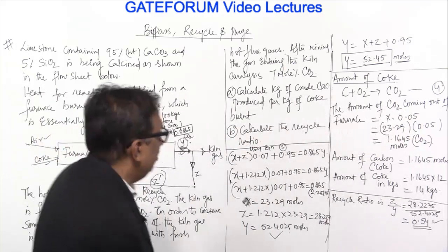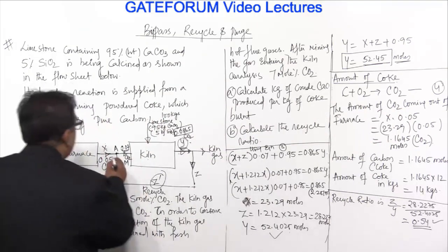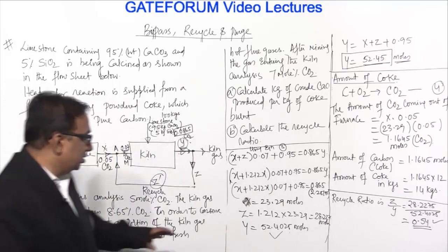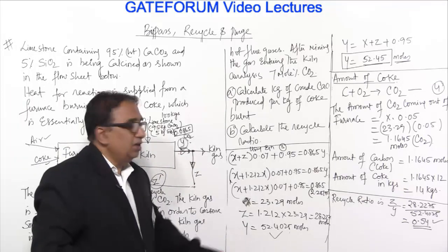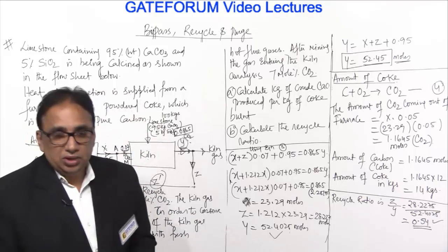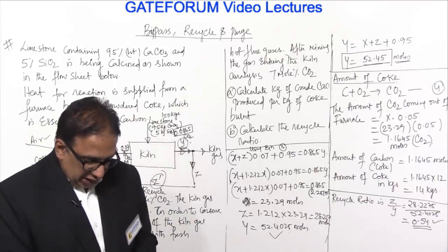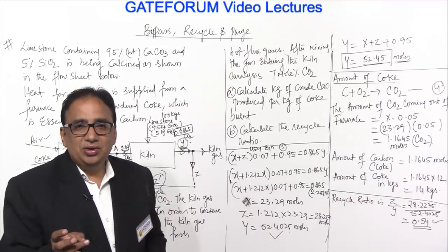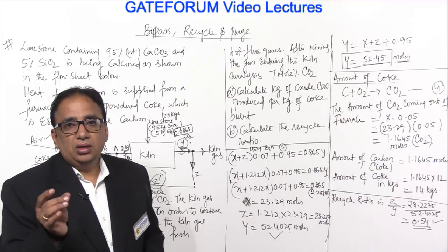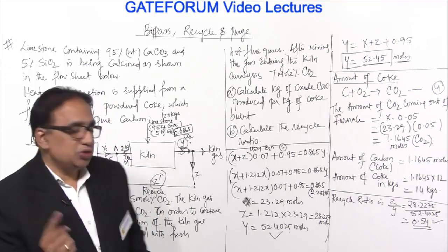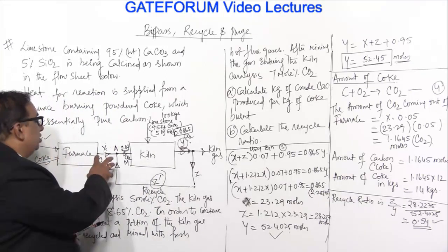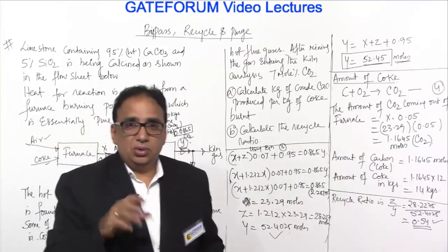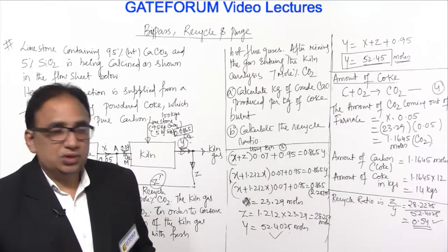See how we have done. We have balanced at each and every point. The key in these problems, I told you, is that for any material balance, first you have to search for the inert materials, tie materials, or you have to solve by simultaneous equations. Because what I am writing here is completely on carbon dioxide, I would get simultaneous equations.